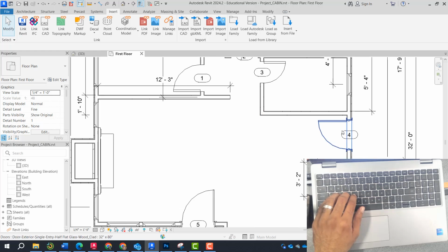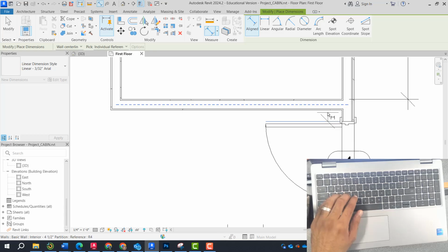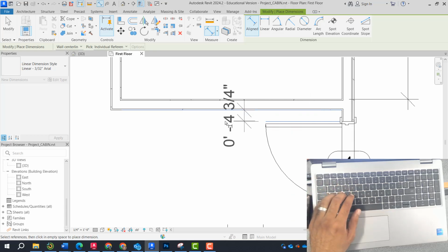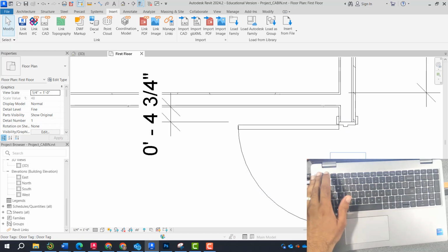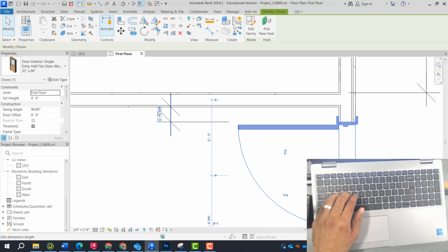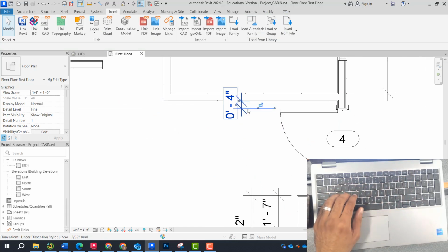To me, I would love to have this door centered, but I also understand usability of space, and I really think we can shrink this space down to 4 inches as the book specified, which is probably the right decision here, to allow for trim, but at the same time having the door open towards the wall.